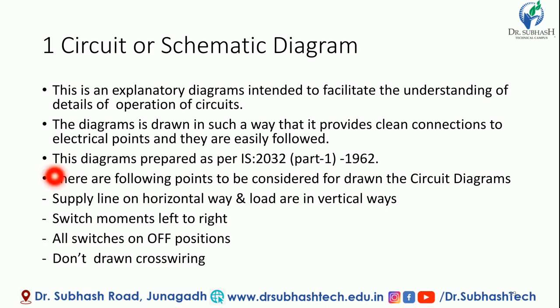All switches should be drawn in the off position, which means you cannot turn on any switch in the diagram. All the switches should remain off in the diagram. Fourth, don't draw cross wiring, which means you cannot cross wire anything in real life.